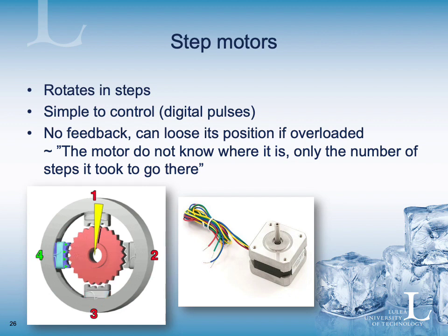For instance, if you have a car with electric gauges, you sometimes can see that when you start up the car, it goes from 0 to maximum to 0, which is normally a calibration sequence for the step motor in the, for instance, RPM gauge. This also looks cool maybe for the user, but the main reason why they do it is to calibrate the step motor.